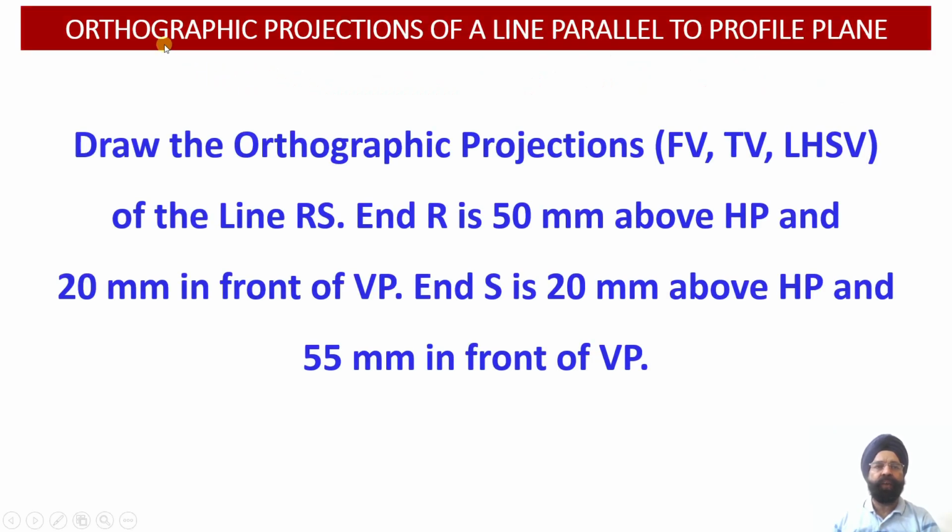Here we are required to evaluate the orthographic projections of a line which happens to be parallel to the profile plane. Since this line is parallel to the profile plane, to begin with we are going to obtain the true length projections of this line onto the profile plane. Thereafter, we will be evaluating the front view projections and the top view projections of this particular line.